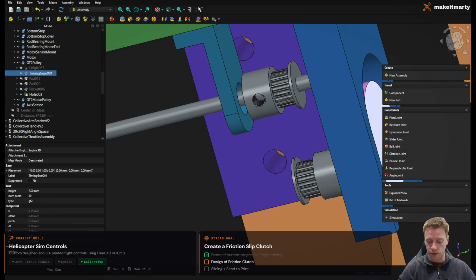Now we don't want to fix it to the shaft. I believe we want it freewheeling, essentially around the shaft, and then the pressure that we give it via the spring should then push against the fixed thing we have on the shaft, and that will transfer the energy.